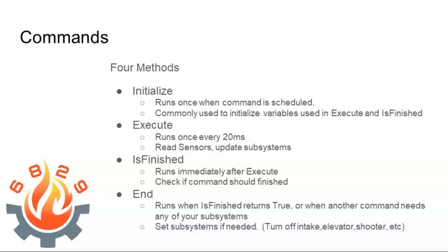But you need to know what your encoder value is now to figure out what the value should be at 5 feet. So maybe on initialize, it reads the encoder value. It sort of zeroes out your encoder value, not zeroing out the encoder on the actual hardware, but just logically doing that. That kind of stuff is done in initialize. Do not run any code in there, just initialize values.